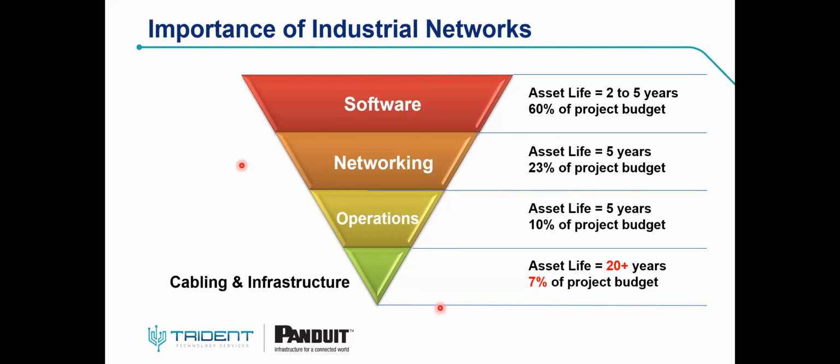You need to know that half of industrial network problems are physical layer related. So it's very important when you are talking about the network physical layer or network physical infrastructure cabling. We need to pay attention to the standards and best practices when you are designing, implementing, operating, or maintaining your industrial network. So maybe a few dollars more in your physical infrastructure, and we can enjoy the plus 20 years you are expecting.